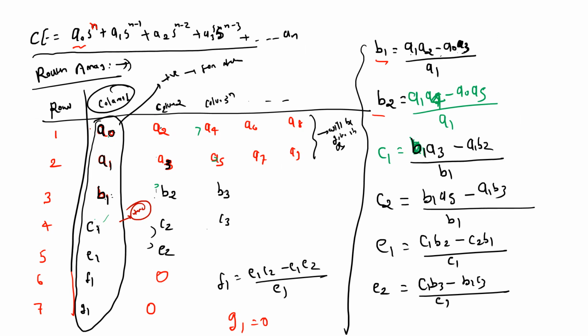The reason is that you only have to solve the closed loop transfer function and you'll get a polynomial in the s domain. While observing the coefficients of the polynomial in the characteristic equation, if the signs of all the coefficients are positive, then the system may be stable or may not be stable. But if any coefficient is negative, then the system will certainly be unstable. That was the criterion I discussed in the previous lecture.